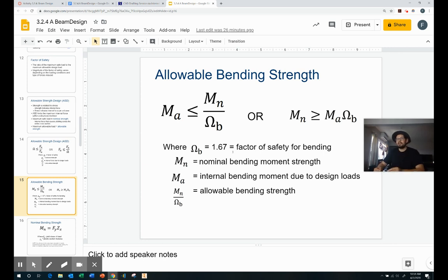So if this beam can hold, let's say, 100 pounds, well, then that 100 pounds better be 1.67 times greater than what we actually expect to ever exist on this beam. So if my load conditions say there's only going to be 50 pounds of force on this beam ever, maximum, the most people that can fit on this beam is 50 pounds. Well, then if this can withstand 100 safely, then it's a safety factor of 2, which is good because it's greater than the 1.67. So that's kind of like the margin of how close we should get.